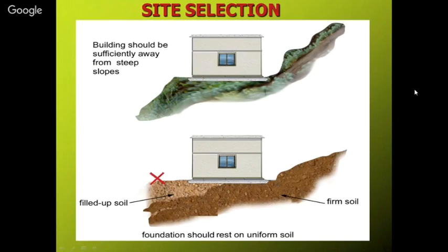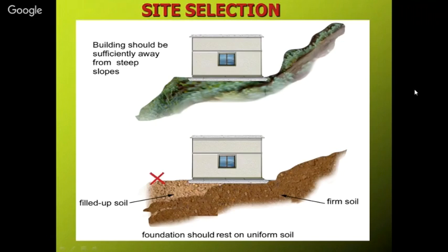Then we can decide the foundation of the building, that yes, this house needs a raft foundation or strip foundation or pile foundation. What is the strip foundation footing? In a strip foundation, the wall has individual footings. Like this, if a wall is there, it has an individual kind of footing like this.